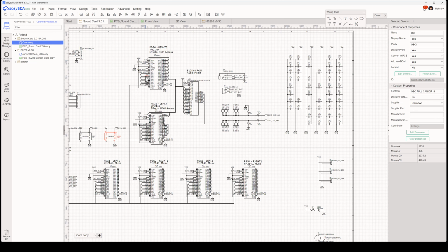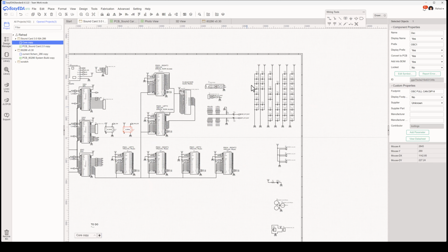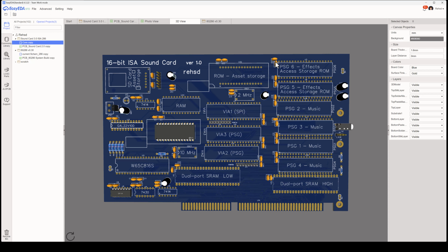If I go back to my schematic, that's probably about it. I've got a bunch of filtering capacitors, or just capacitors, that I put around all the different ICs. I put a pair, which may be overkill, but I have a pair. I typically do a 0.1 and a 0.01 microfarad for every single IC. And then I just have some additional supplemental caps. There's 4 of them. Typically I like to have one down here, here, and here, because that's where power comes in on the ISA slot. It was just too much mess down here. It was causing too many problems.